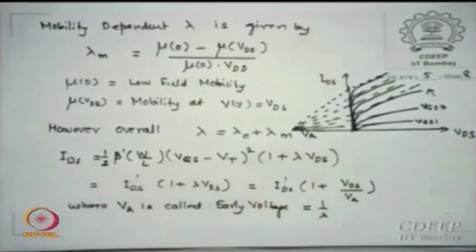So when SPICE does it, it does not know anything. You give it some physics, it starts solving, and then your value of IDS is not the same as what you thought analytically. But why do you need analytical then? Because which value to start the simulation with? You need an initial guess. It is a non-linear equation. If you make the guess wrong, there is no possibility of reaching the solution because it is already divergent. So in solving a nonlinear system it is essential to know the initial guess, and a guess very close to correct. Analytical solutions do give that guess.